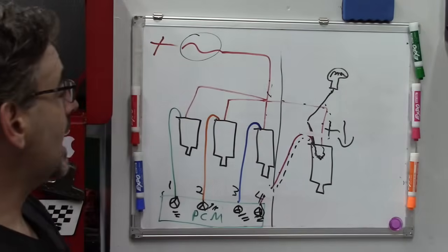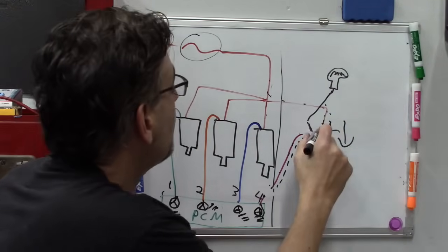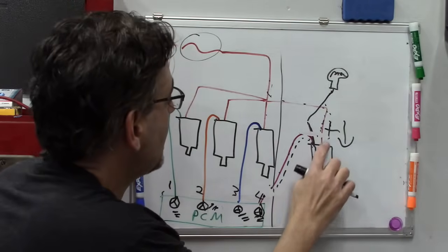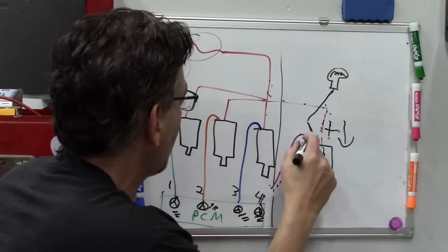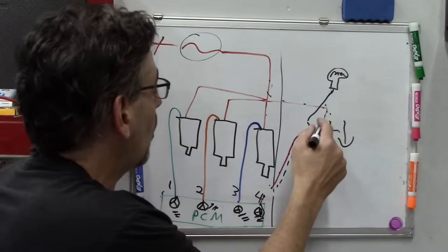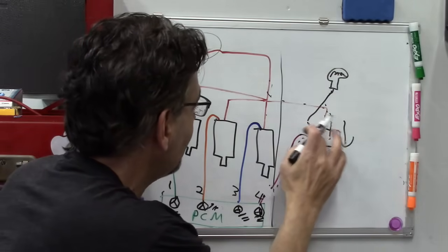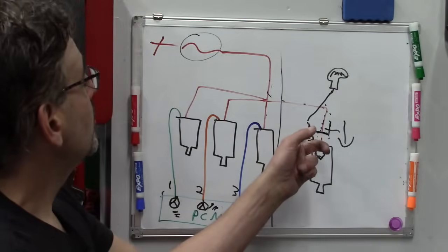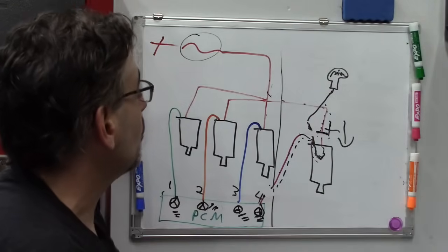When I disconnect from the injector, we've got our power here, but then there's no connection of that power through the coil in the injector over to this wire that I'm back probed on. Now that we're disconnected, that power ends here. So when I disconnect that connector, the light goes out.